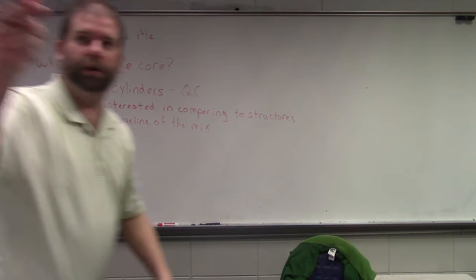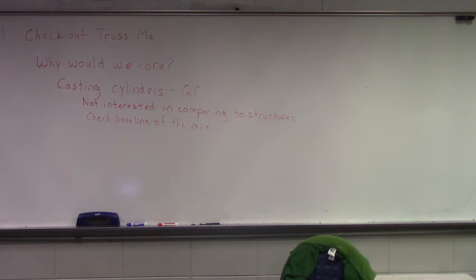So when you're doing projects like these, most of the ready mix producers, I shouldn't say most, all of the ready mix producers in the Twin Cities are savvy enough that they're using some sort of water reducing admixture. So that will get you your workability without altering that water to cement ratio.